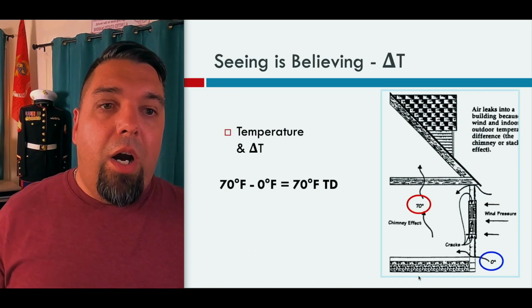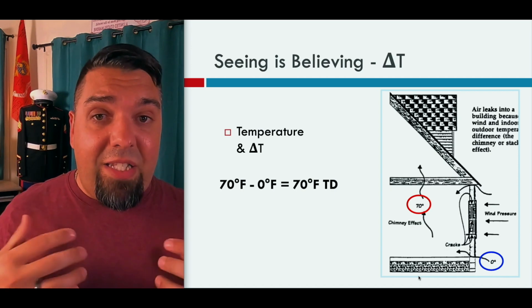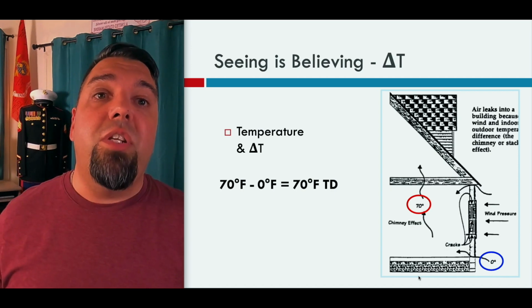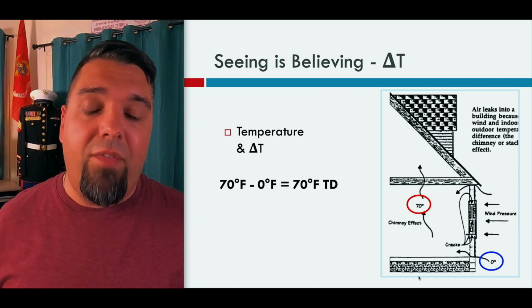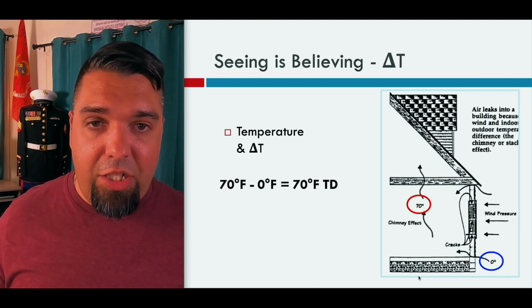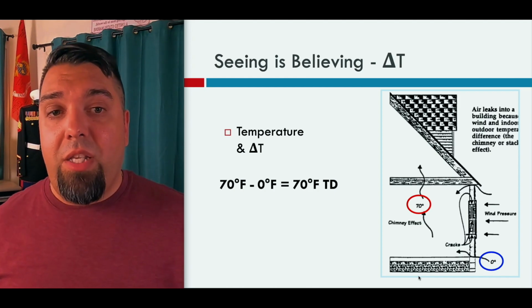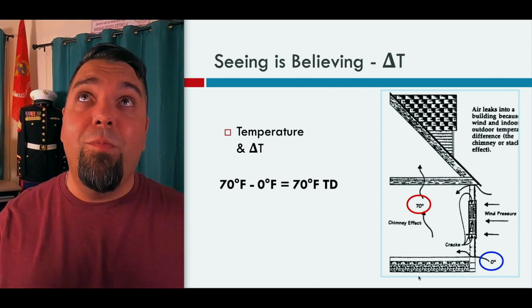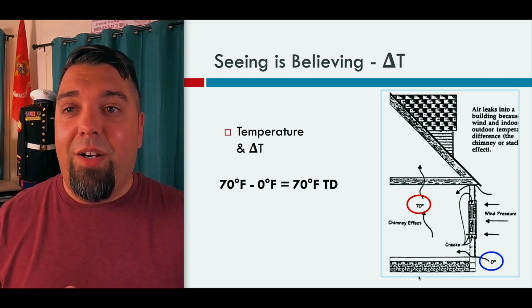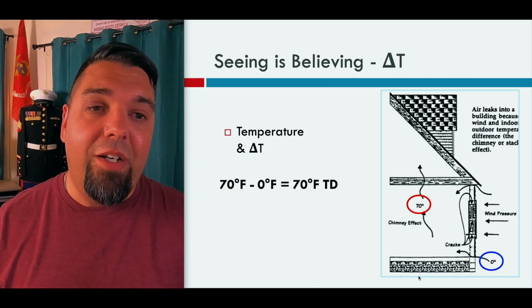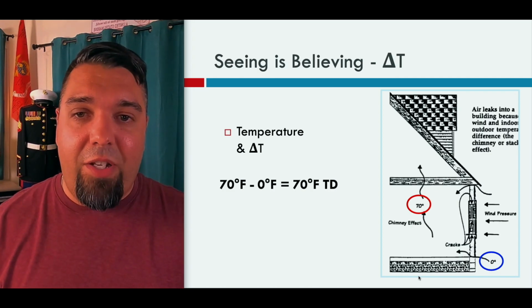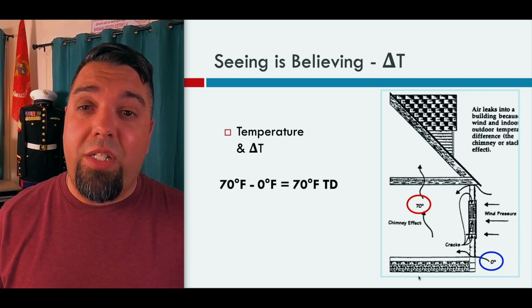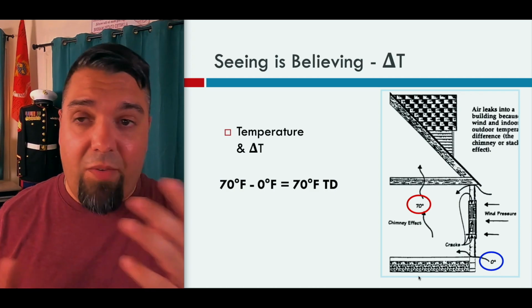All right. And then, of course, in order to make this math work when we get to heat loss, you need to know what your design temperatures are going to be. Obviously, this is going to be your indoor design conditions minus the outside design conditions based on tables 1A or 1B, not whatever you think it's going to be. So very, very important here. In this example, we want it 70 degrees inside. Just so you know, code is 68 to 72. 70 is right in the middle.